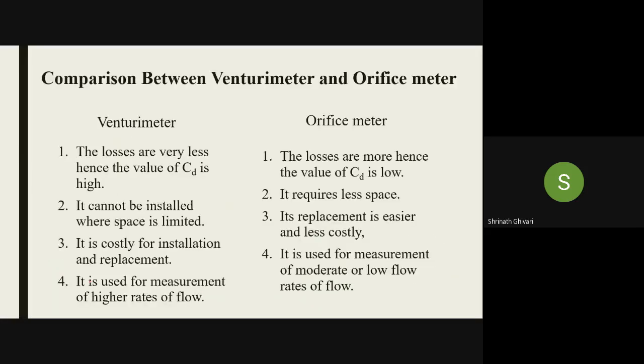Now we'll see the difference between the Venturi meter and Orifice meter. When are we going to use a Venturi meter and when an Orifice meter? Both have a similarity: they measure the rate of flow or discharge. In a Venturi meter the losses are very small, hence the value of CD is high. Here the losses are less, that's why we get a value of 0.98.